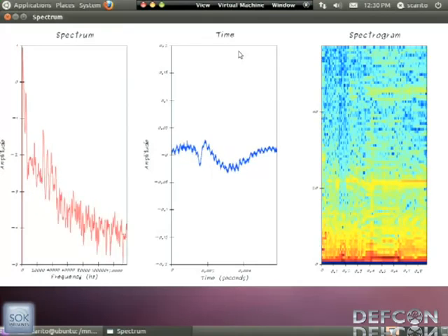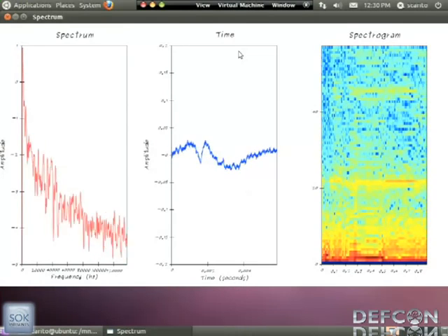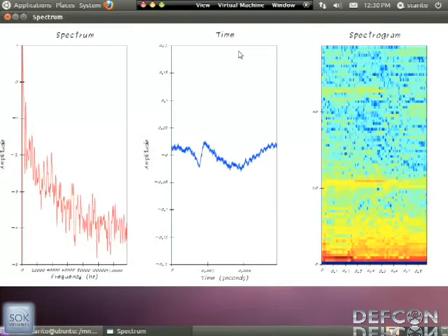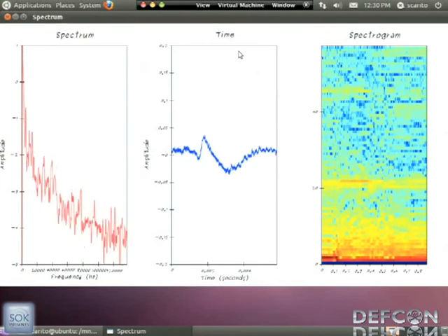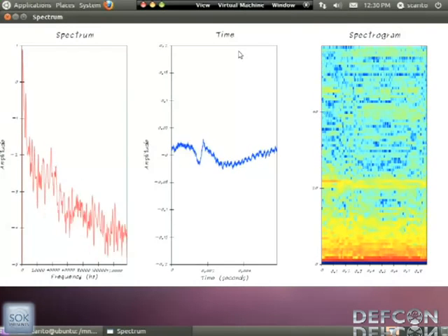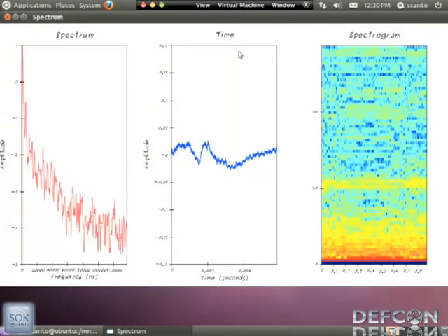And the other thing, which I haven't actually seen yet, which I'm a little surprised by, is this thing operates in the Wi-Fi band. And there's a lot of noise. I'm not exactly sure why that's happening. That wasn't happening before. But what you do see occasionally is these pulses, towards the top end of that. And that's actually Wi-Fi signal bursts from the thing transmitting.